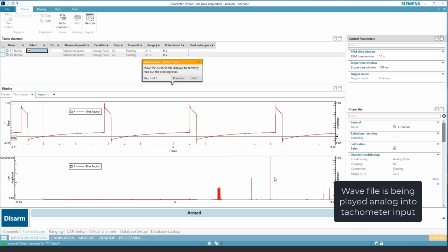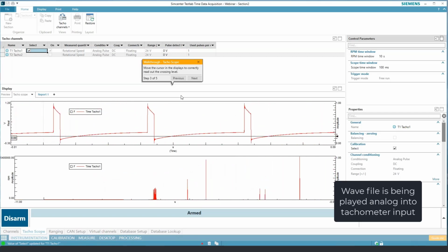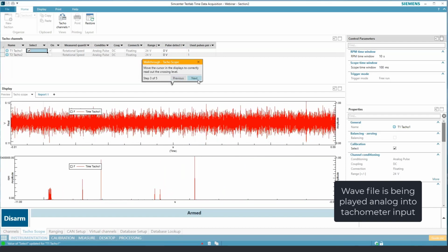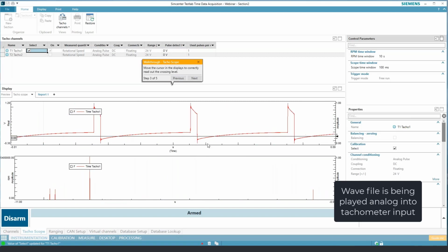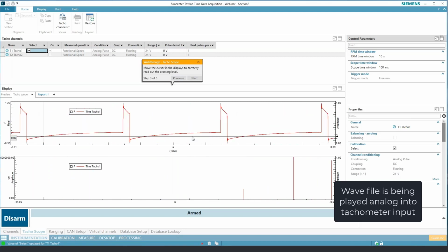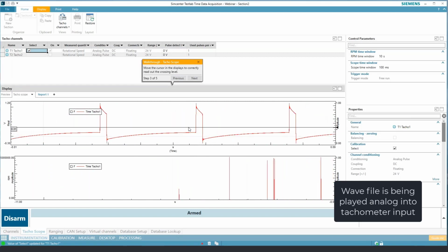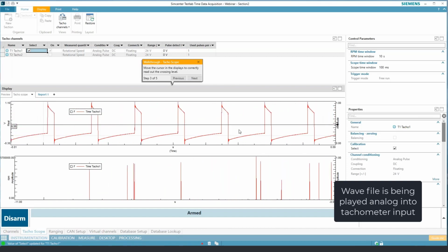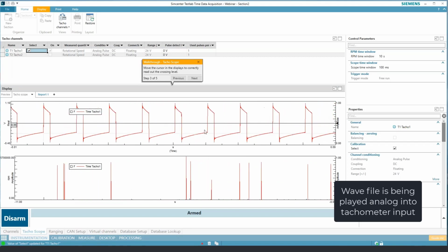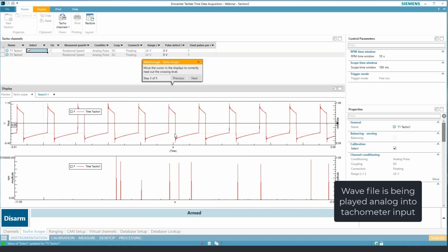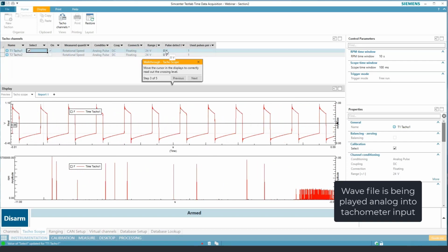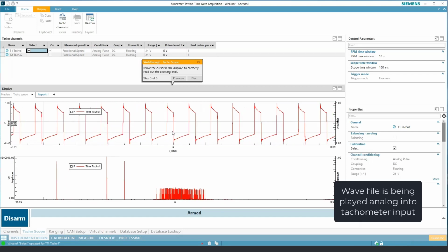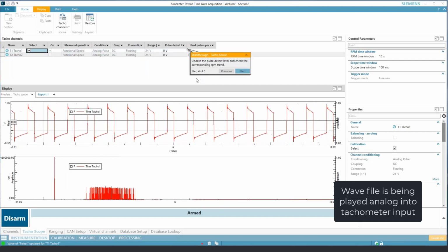Here's some more erratic RPM pulses. So what it's telling you to do in the guide me is to find a clean area of the tach. So I'm going to move this around visually to find, say here at about 3.5 volts, somewhere in the middle here, where I don't get these weird multiple crossings. Okay. Now it's still being calculated at 0 volt just because I've moved the cursor. This lower display hasn't really changed yet. That's the next step. I go next.